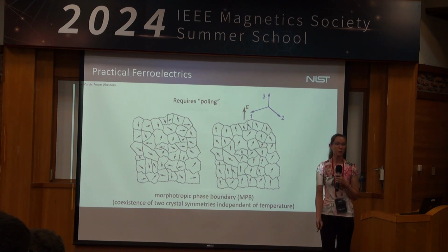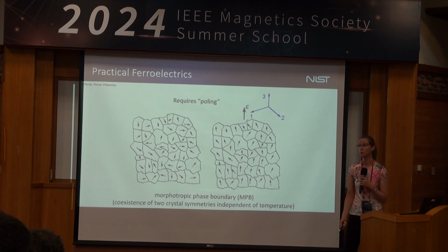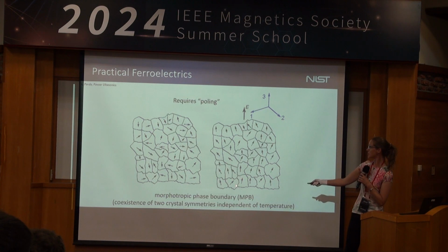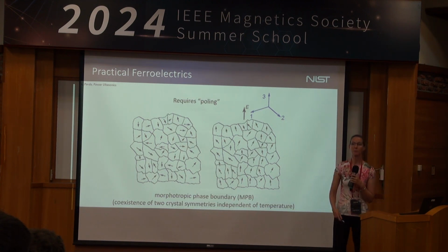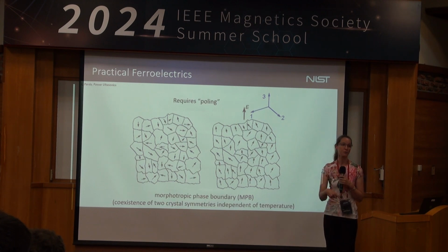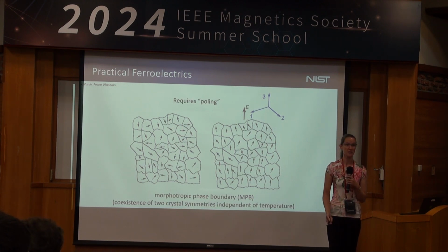One very important process in any ferroelectric material is something called poling. This basically means you have to apply a very large electric field at a fixed temperature. All of these depend on the particular material you're working with. That causes alignment of the crystallographic axes, and when you do this, you are now able to recover the piezoelectricity for the sample.